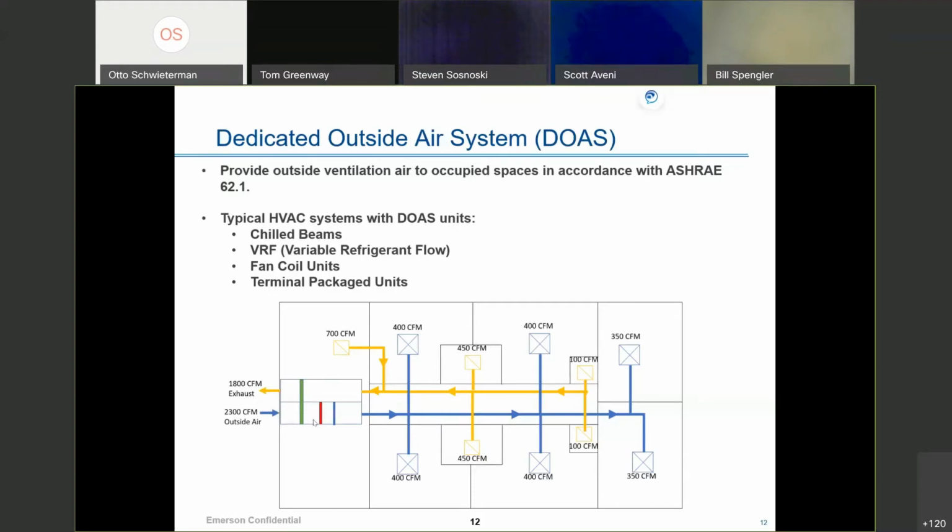This really reduces the load on the cooling coil for the cooling condition. So you may actually be able to undersize this cooling coil compared to what you would if you did not have this heat wheel. It's also much more efficient than trying to mechanically cool that, instead of using the energy recovery and just exhausting all of this air out of the building that you would be exhausting anyway and not using that energy as a reclaim.